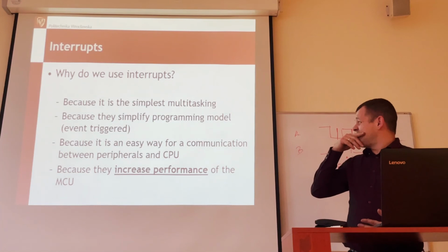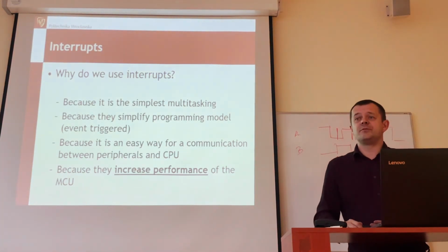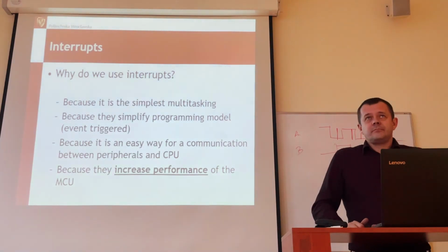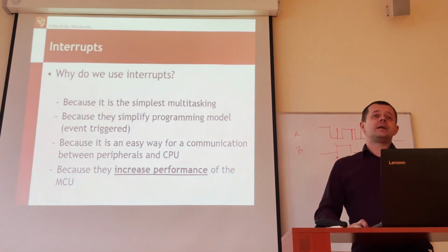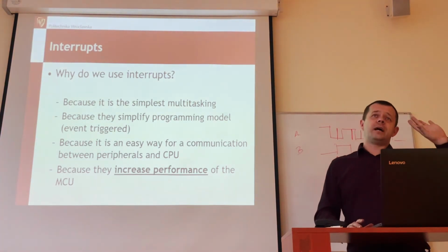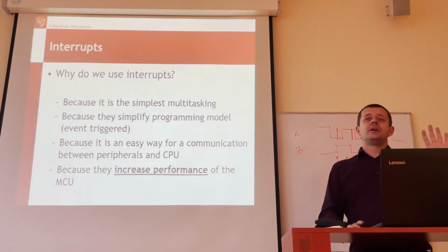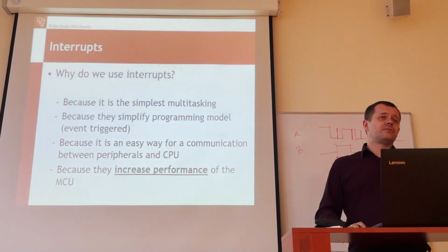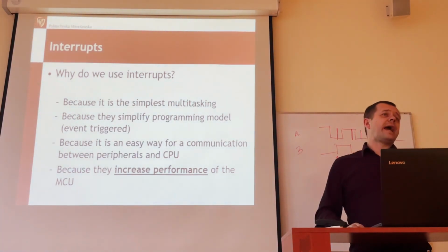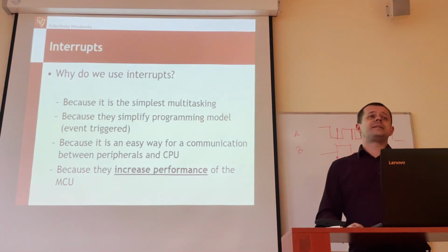Because it's an easy way for communication between peripherals and the CPU. With interrupts, if something occurs, for example, if a conversion finished in some ADC converter in the peripheral, naturally the CPU may ask if it finished, so it may test the status.